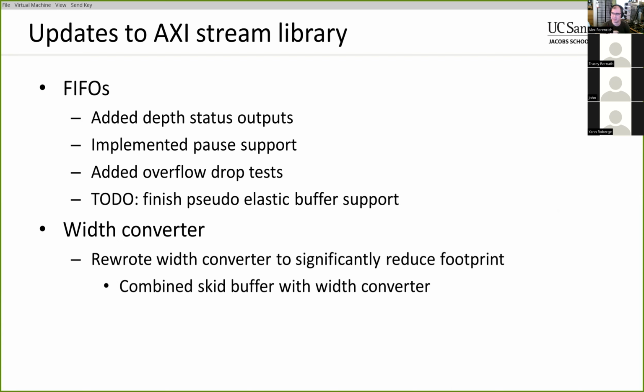I also went ahead and added pause support to the FIFOs. So this only adds a couple of LUTs if you enable it, and it gives you a pause request input. So if you assert that, it'll wait till the end of the current frame and then block traffic from leaving the FIFO. So this can be used to terminate the pause requests for pause frame support, and it can also potentially be used to drain the data path on the RX side. So this can potentially avoid a few problems with taking links down.